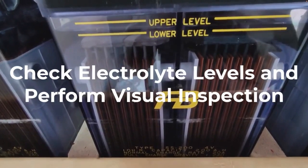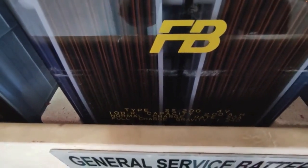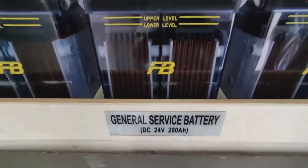Now, the battery bank to be tested must be fully charged and not overcharged. The individual cell voltages or specific gravities should be balanced, indicating that all cells are in the same state of charge.